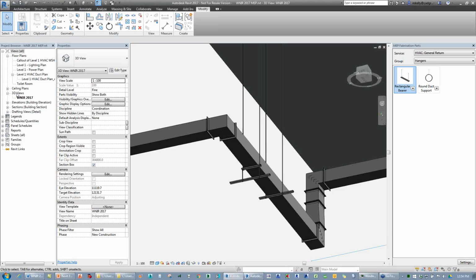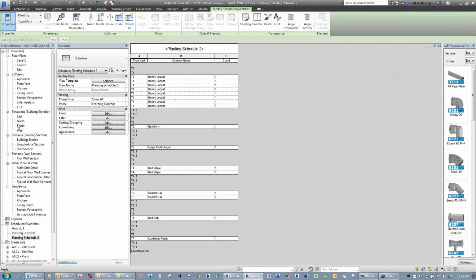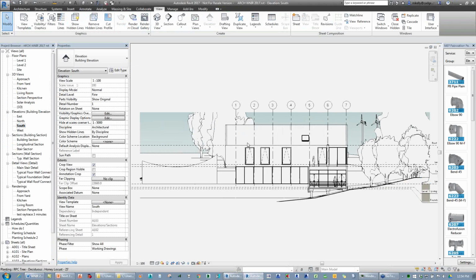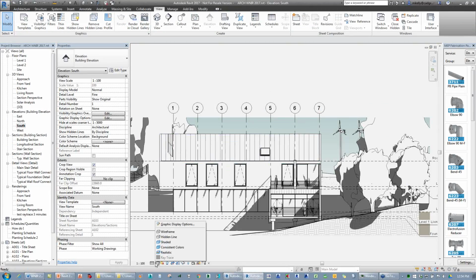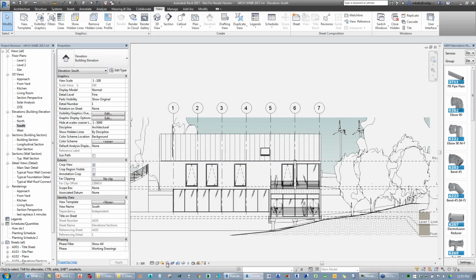Interesting. Okay, I haven't actually tested that. I would assume that it will use raster setting, and that's simply because if you think about it, the way that Revit's displaying the graphics, it's in a shaded view. If I change that to vector, then effectively, I guess all of that shading information would go. That would be my thinking.